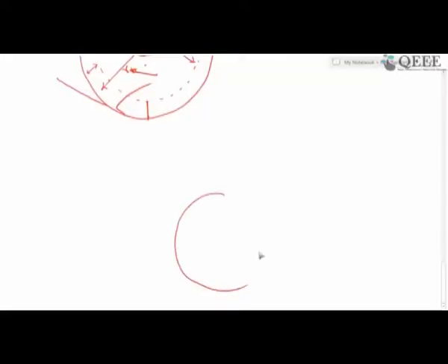the definition of the involute suggests that a string has to be unwound, and as the string is unwound, any point, for example the point at the tip, will form an involute, right? So in the position that is shown here, the tracer point, as the string is unwinding, this free end of the string is tracing out the curve as shown by these dotted lines.